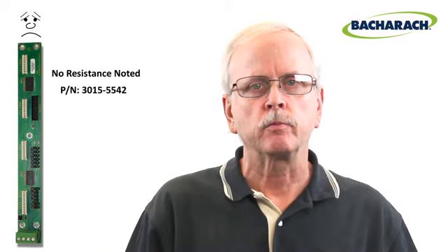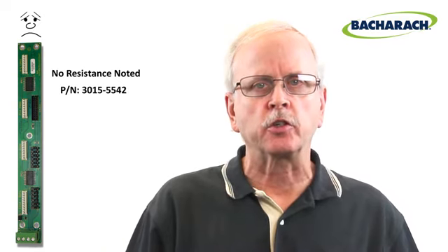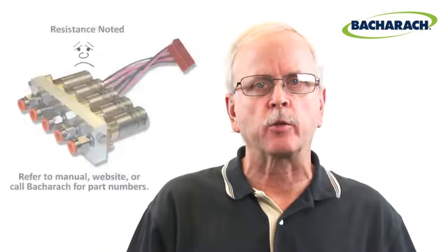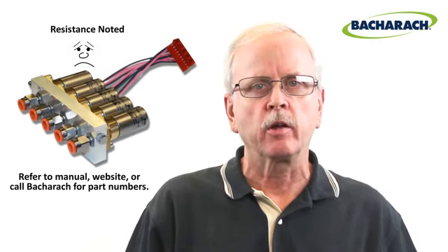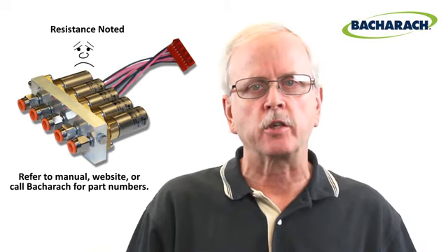In this case, you should consider replacing the printed circuit board that controls the solenoid. If you do notice resistance, it indicates that the PCB is sending the proper commands, but the solenoid is apparently not mechanically activating. In this case, you should consider replacing the suspect manifold.